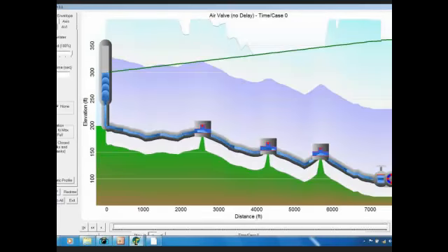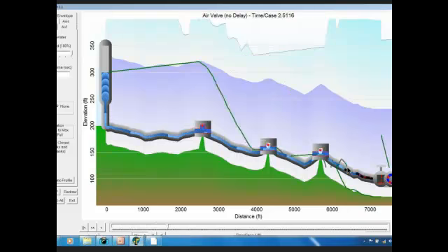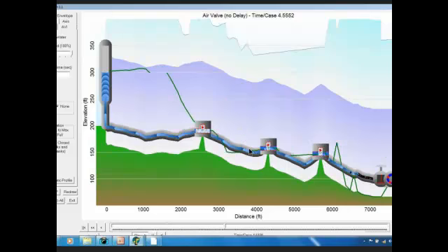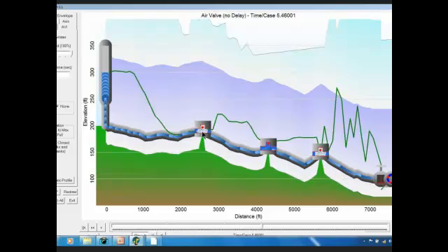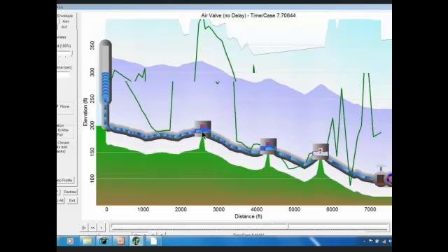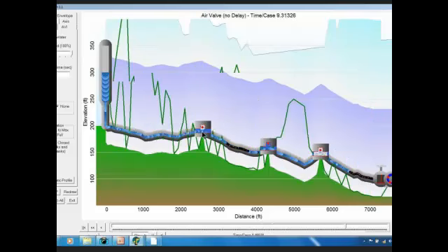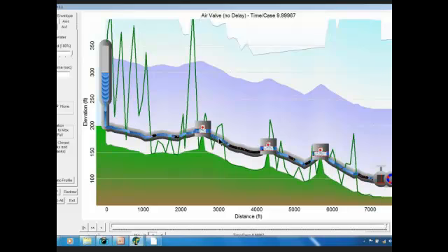Now here's one where we have air valves. Now when this closes, you'll see the pressure surge goes down, and you'll see these air valves activate, and you won't see cavitation. But something does happen that I want to point out here. So here we go. Now you see there is some cavitation here, but nothing here. The air has come in. Now watch here, the air goes out and you get a bang. And once that bang happens, you start getting cavitation. Now these were air valves that weren't releasing the air slowly enough.